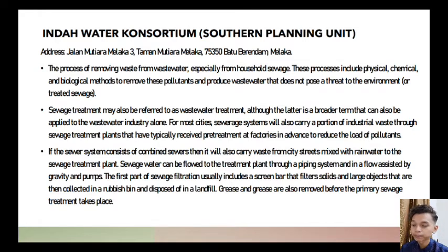The first part of sewage filtration usually includes the screen bar that filters solid and large objects that are collected in the rubbish bin and disposed in the landfill. Grease and oil are also removed from the primary sewage treatment that takes place.